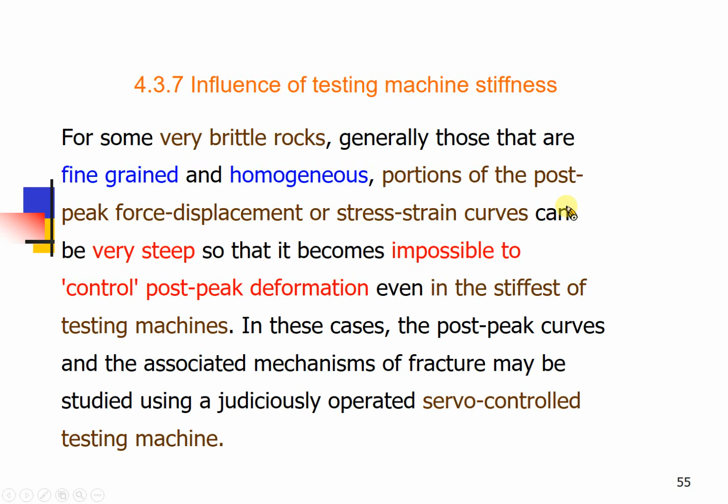Like loading, unloading, loading, unloading, and finally you can have the complete stress-strain curves. How to make the servo control? First, you need to sense the information or the response. You can use the load subject to the displacement, or you can use the displacement, including vertical displacement and horizontal displacement, to detect the condition if the rock already goes up to the peak stress.